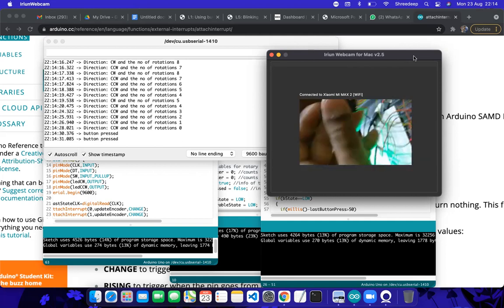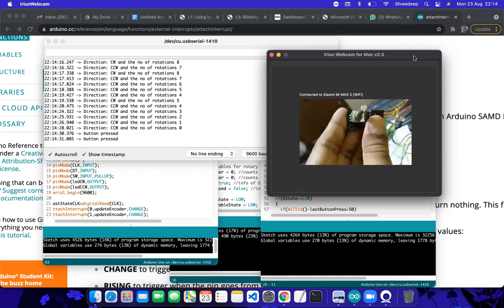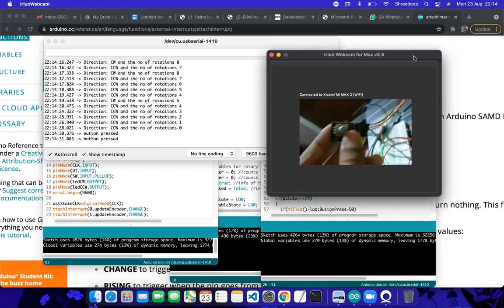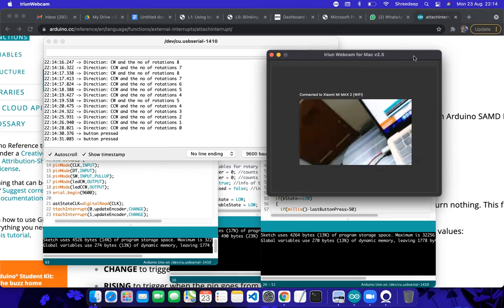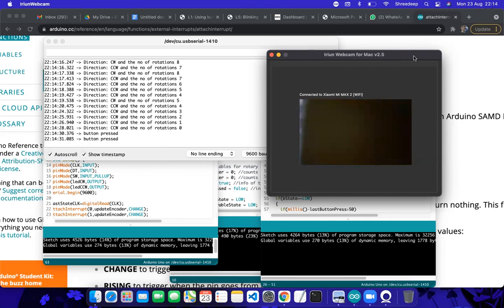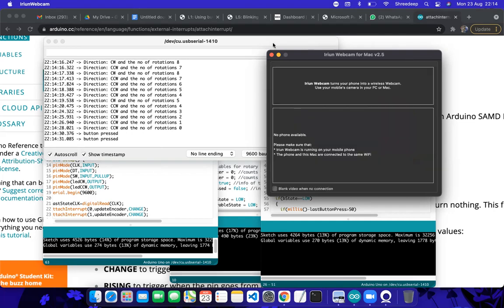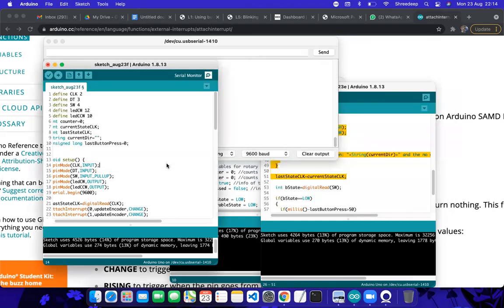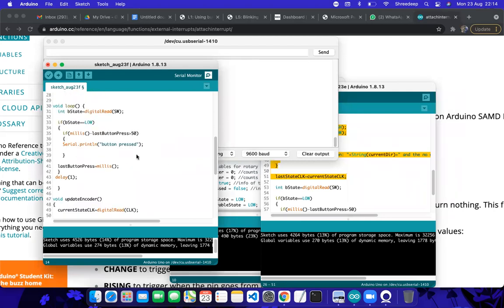And you have a button. So see, the interrupt and IO, two things can occur simultaneously, and the operation is quite straightforward. You could have asked, what's the big deal, because you have already done everything in the program. But see, the main program becomes quite small, quite simple. If you have more sensors to be hooked up with a microcontroller, you could have done the same thing within the loop, which cannot be a part of, let's say, the interrupt. And you have to choose.